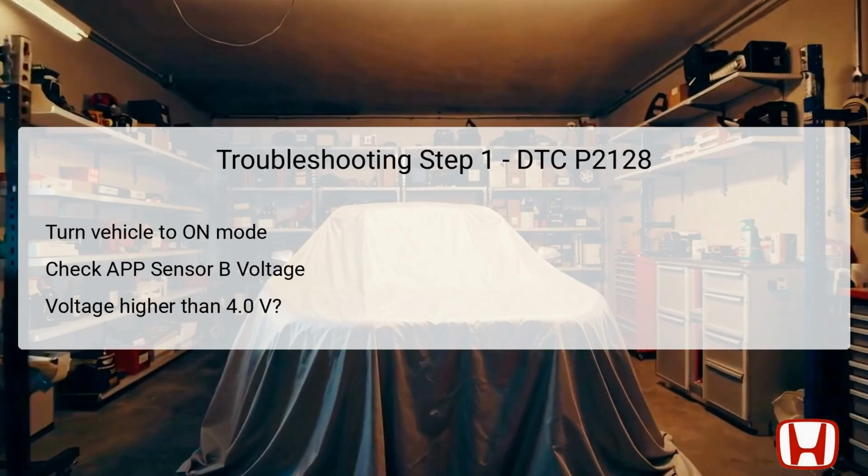The first troubleshooting step for addressing DTC P2128 involves turning the vehicle to the on mode. This action powers up the vehicle's electrical systems and allows for diagnostic tests to commence. Next, it is essential to check the output voltage from APP sensor B using the Honda Diagnostic System, HDS.